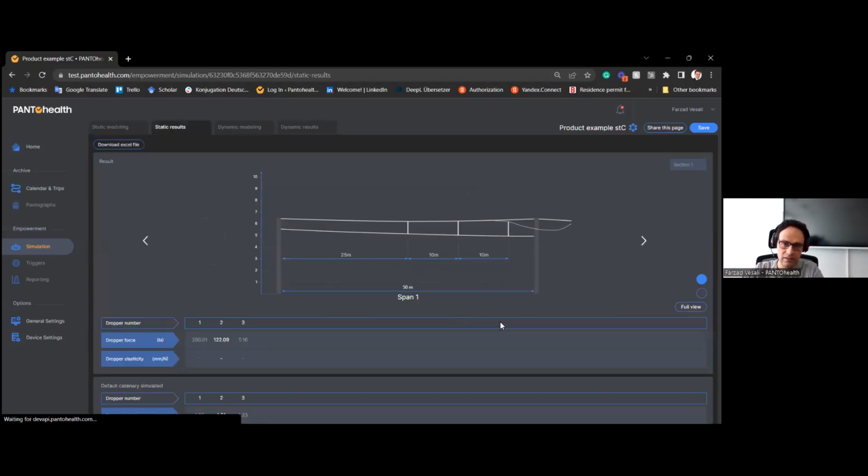The result is that it depends, because if you increase the tension of a stitch wire a lot, the messenger cable over the stitch wire would be released, and because of this, the length of the dropper will be reduced. But there is some optimum value in between.